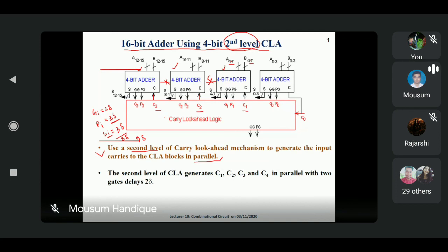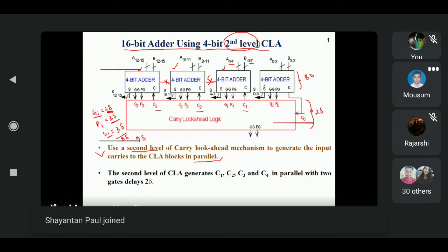And when we were discussing the 4-bit carry look ahead adder, you remember the generate function, the carry generator, denoted by Gi. It always requires 2 delta. Okay, it is always required 2 delta. So this particular portion requires 2 delta. And this particular part is the generator, and generating the sum is fixed. Fixed means what? It is 8 delta.